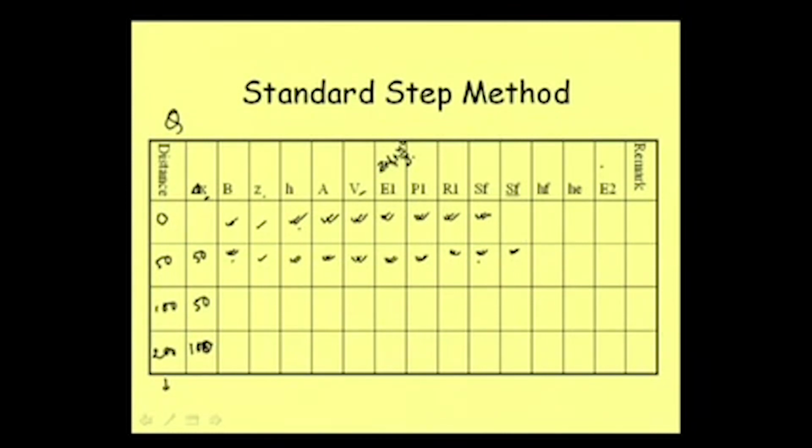How this SF we are calculating here and the SF we are calculating here, between this 0 point and 50 point we are calculating both the SF. So this SF bar will be basically the average of these two values. So combining this we are calculating the SF bar. Okay. Then once we get the SF bar, we can calculate the friction loss, SF bar into delta x. Then once we know the V1 and V2, here this is our V1 and this is our V2.